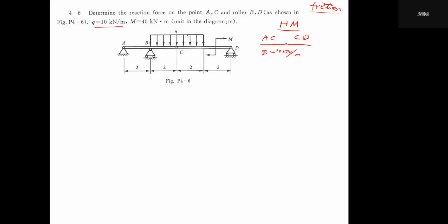So how do we treat loads like this? Please focus on my conclusion. We use the resultant force FQ, which equals the area of this shape. If we consider the whole distributed load q, then FQ should equal, because this shape is rectangular and its length is 4 meters, 4 meters times q, right?